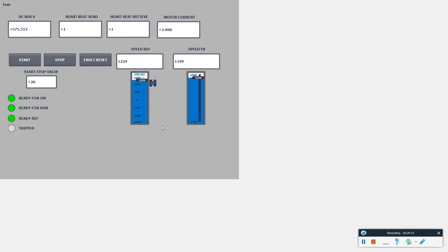So you need to make a better script to consider safety situations, like if the connection breaks between your SCADA and the drive, it should immediately stop. All these things you can make intelligent logic to do. So I am using this heartbeat to do that.